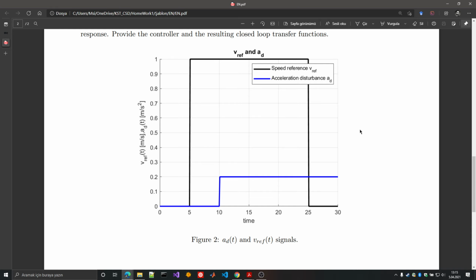You have to provide a transfer function that has 2 inputs, so a MISO system, which you can do, by the way, by putting transfer functions in an array using a comma separator, a multiple input single output system, because this is one of them.